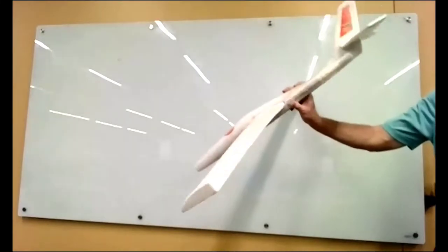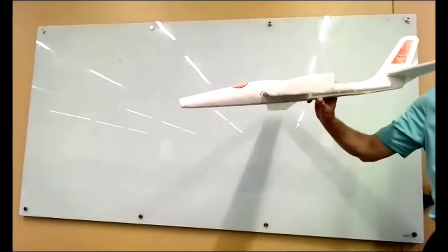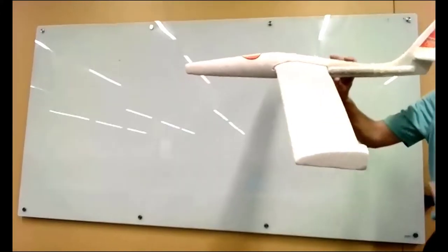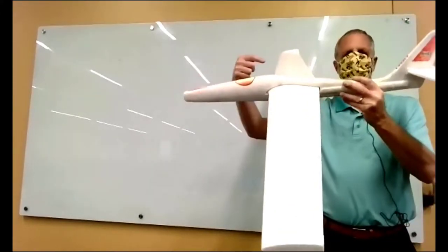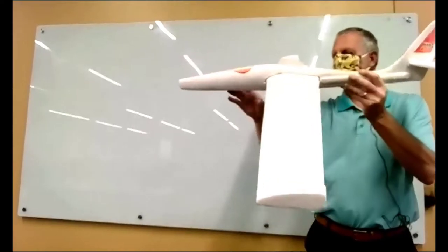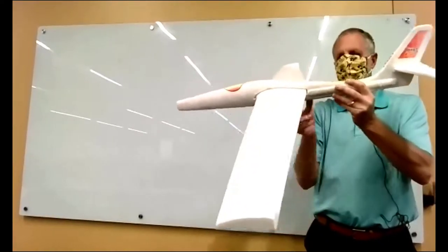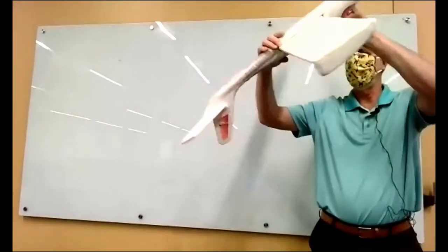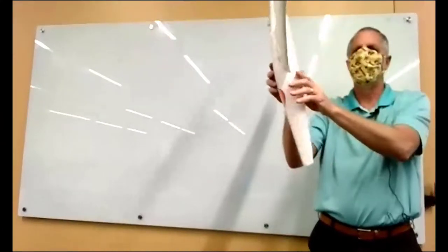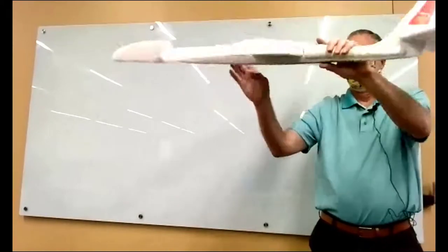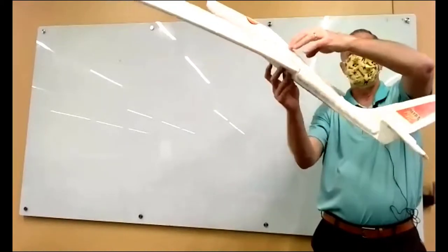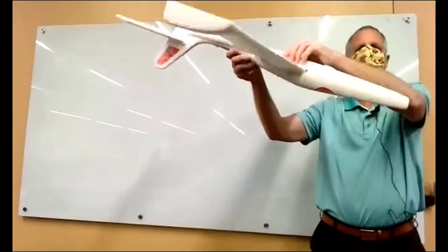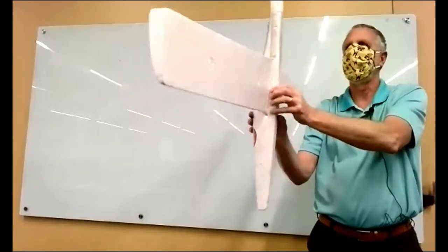Okay, so here we're talking about the pitch rate and the effect on the lift, drag, and pitching moment. So remember we got flow coming in this way, right? And now we're talking about an airplane pitching, so nose up is positive pitch. So we're talking about an airplane spinning slowly, because we're not talking about fast spins, spinning like this. So the CG is pretty much near the center of the wing, right? So the wing is rotating, but what do you see sweeping through the air pretty quickly?